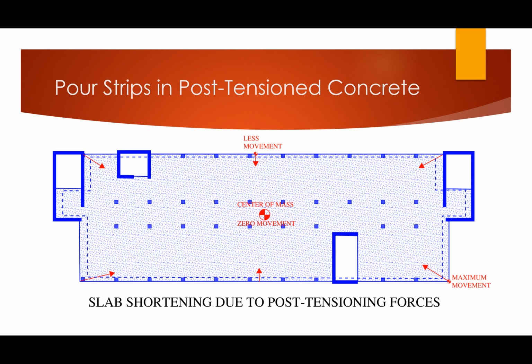So your four corners here are kind of the locations where you're really going to see maximum movement within the slab, right? And that movement itself is not really the problem. The problem is that this movement is restrained in a lot of instances, especially here, right? So think about your concrete shear walls. By definition, those are designed to not really allow, or at least to resist, horizontal forces. And so they're just fighting against your slab, right?